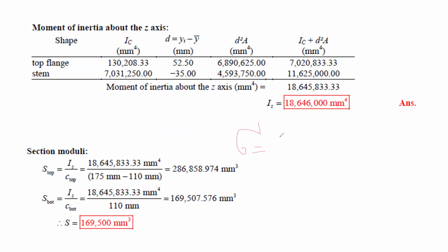So stress is equal to 1200 Newton meter, sorry, into 0.004 meter. This is Y. And then this needs to be divided by I, 4 times. So tell me what should be the stress? Professor, so it's 257, 427, 8.6. And this came as Newton per square meter, which is equal to Pascal, right?